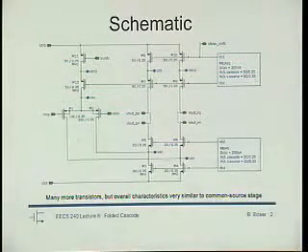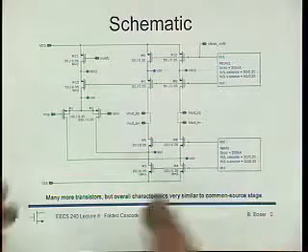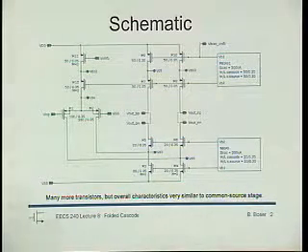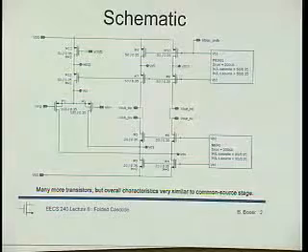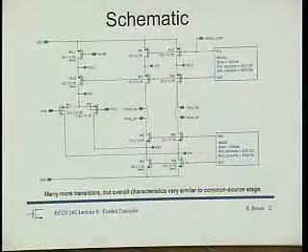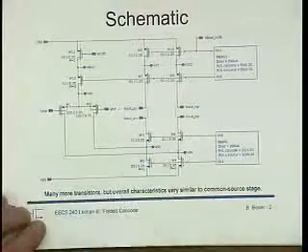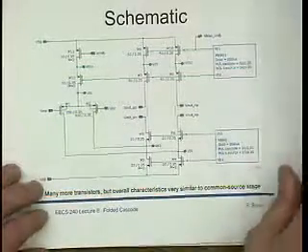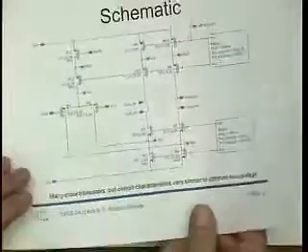Increasingly, that's not so much a problem anymore because technologies have gotten so fast that, again, we have 5 gigahertz FT devices and we build a 200 megahertz amplifier. We perhaps can get enough phase margin no matter what, right? But that's an argument. And that is also an issue of the folded cascode design, that we have the two types of devices in our signal path. The non-dominant pole comes from one type of device, and the transconductance from the other.